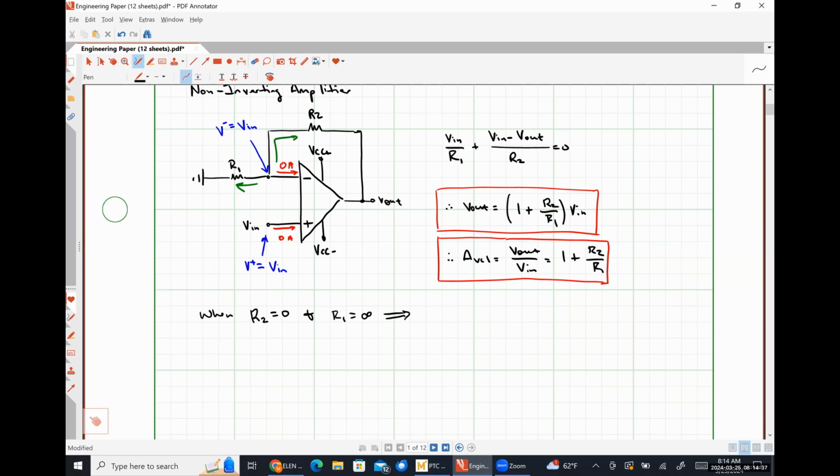It will not be 0. Yeah, exactly 1. So our closed loop voltage gain will be exactly equal to 1. This configuration is what's known as a unity gain buffer. It is literally just a special case of a non-inverting amplifier.